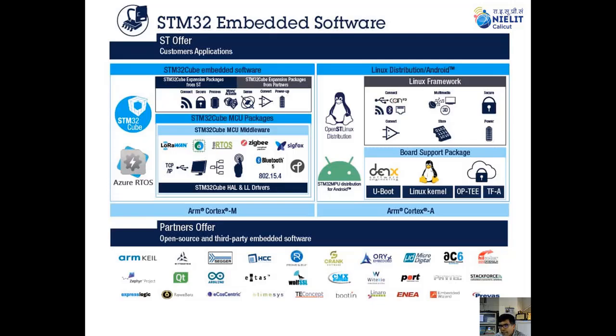Now for high end, for example, if you are targeting the Cortex-A application series, the things will be different, because there we sometimes need to port an operating system such as Linux, or work with bootloaders such as U-Boot, etc. In that case you can use the build environment and start developing various applications at the high end, at the operating system side. That framework is also available in the community, so we can utilize it.